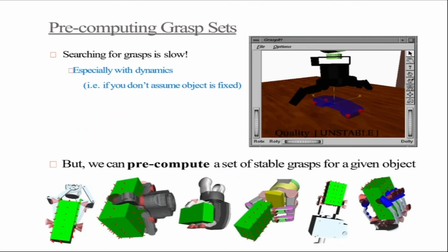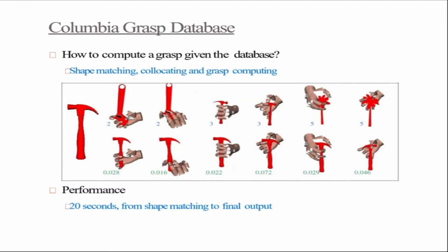Now, people have looked at pre-computing grasp sets. For example, if you're given a cube, how to hold it. So this is a cube, and you're supposed to hold it. You can go and hold it in that order. Now, there are other solutions also. These are all solutions. We have seen that in the null space, you can get multiple solutions. Okay, so these are also solutions. So the grasps can optimize a function and get into those points.